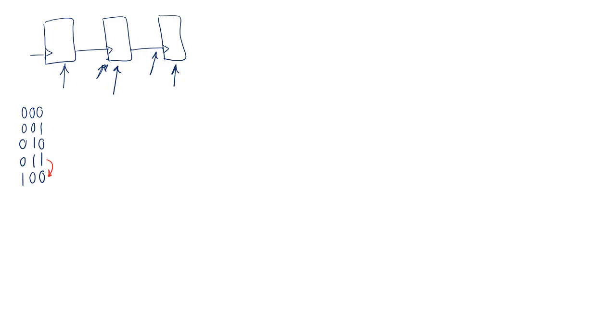When you go from 011 to 100, from 3 to 4, you want to make sure that this 1 goes to 0, this 1 goes to 0, and this 0 goes to 1 at the exact same time. Because if they don't happen exactly at the same time, you might eventually get to 100, but imagine that these two are happening sooner than this one. Then you go from 011 to 000, then Q2 becomes 1 and you get to this, right?